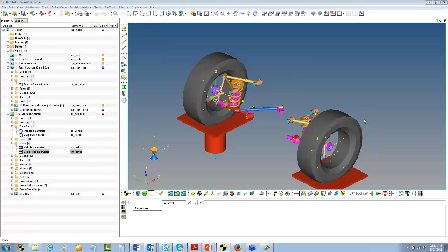Right. Rollover condition is different. For that, I guess you have to do some kind of full vehicle analysis, and this half vehicle analysis won't be enough for that. And yes, it is different from body roll, because your body roll might not be much. Body roll is generally defined with respect to tires, and this rollover condition is of the complete vehicle globally.